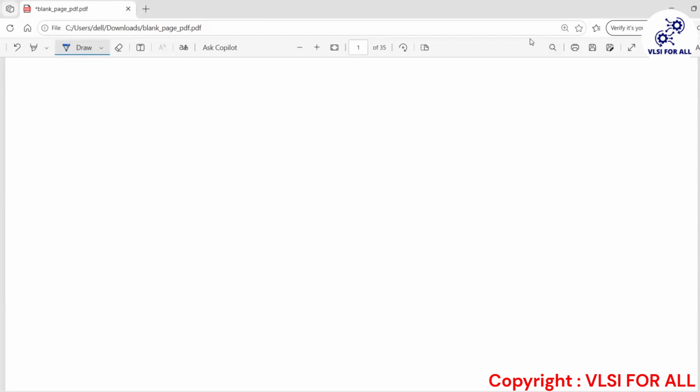So in the last class, we talked about the process design kit, PDK. What is the process design kit? Then we talked about some analogies. Then what are the categories where we have discussed the PDKs? The device models, design rule files, standard cell libraries, then technology files. Then we talked about the LVS and the PEX decks, then GDS2 and the documentation process.